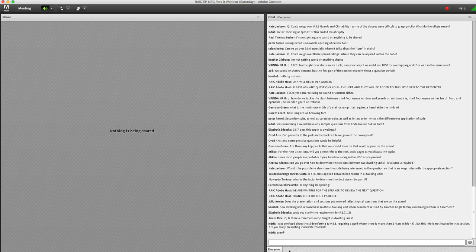Sorry for the pauses in between, but I just wanted to be able to answer your question as best as possible. So I did have a question on 9.7.2 on windows: must conform to which energy requirements? The energy requirements are part of the performance expectations for windows, doors, and skylights. This would be related to actually complying with 9.7.3.1, which is general performance requirements, which refer in terms of performance requirements to 9.7.4 and 9.7.5.